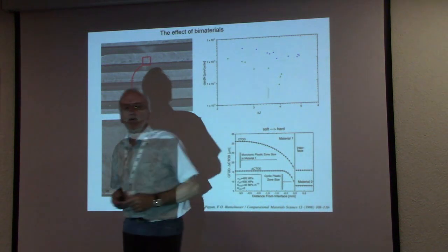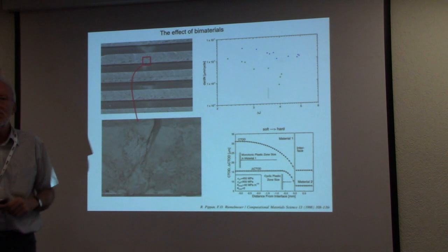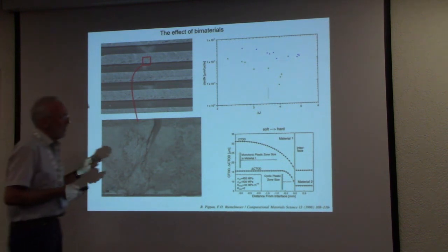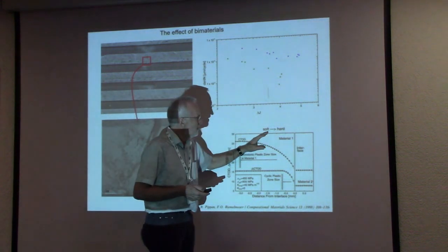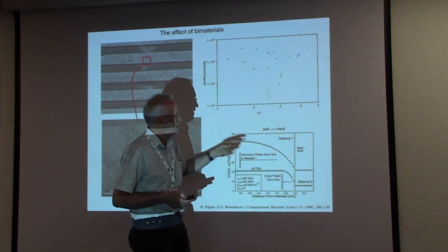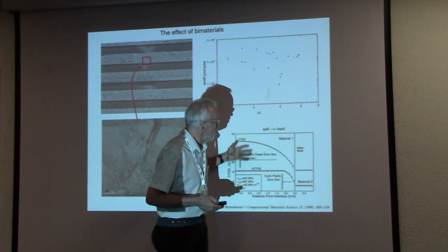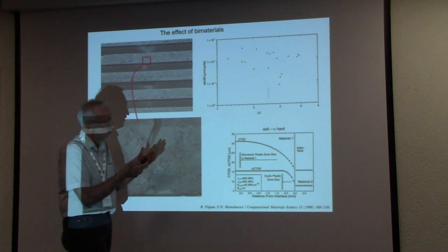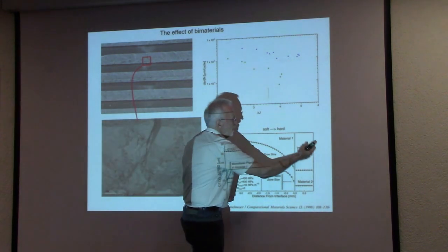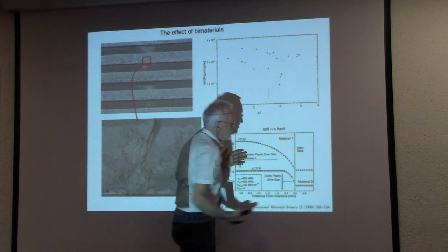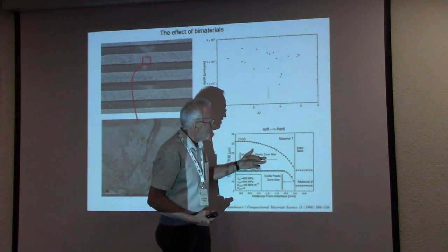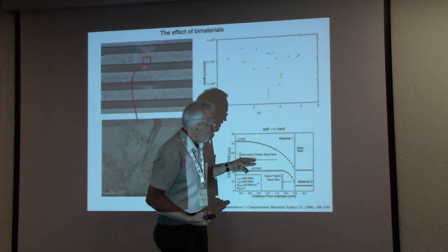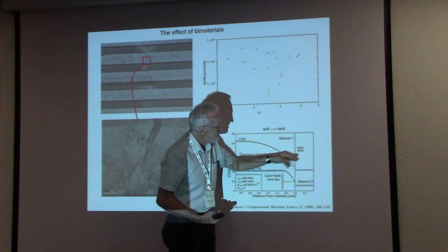This first seems to be a bit strange, but one can understand this is simply a fact that the plasticity in front of the crack is, in principle for the film, a full-scale yielding on an elastic substrate, and the crack tip opening displacement decreases when the crack comes to the elastic interface.